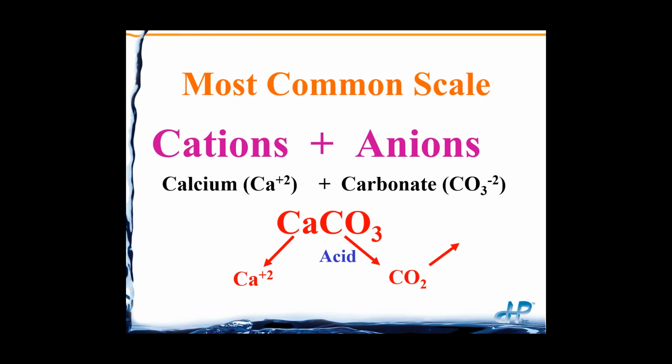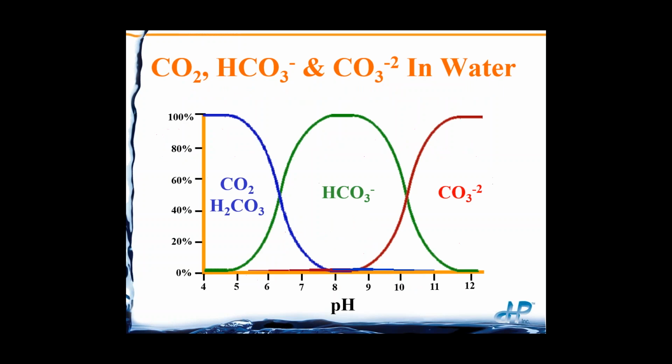But that's going to be the only easy one. And again, it's this relationship. So this is the relationship between CO2 and pH. Below a pH of about 5, all of your CO2 is in dissolved CO2 form, which you can call carbonic acid. Well, as the pH goes up, when it gets to the neutral range, here's where most of our natural waters are. The pH has converted most of the CO2 into bicarbonate ion, but that's a single charged ion. That's not a problem for us.